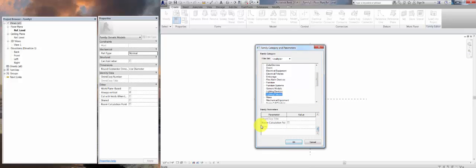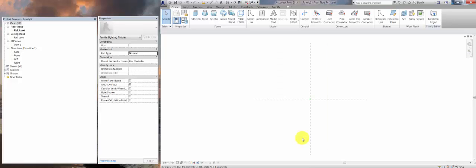You'll also notice when we scroll down that the host is listed as nothing. In other words, it is not hosted. Next, we want to think about the shared parameters we want in here. You'll probably want to jump into making the 3D content first. However, 3D content is the easiest part. All the other components that make Revit really smart and beneficial are the other things besides the 3D content, the information that you have embedded in it.